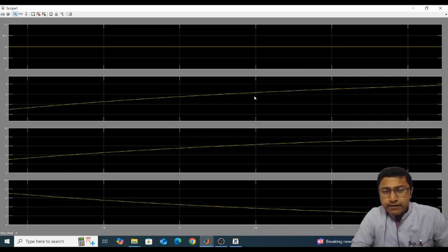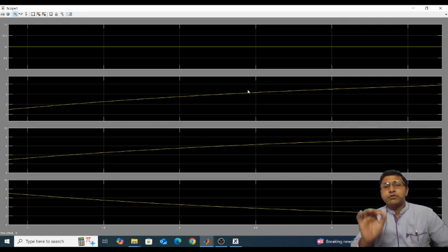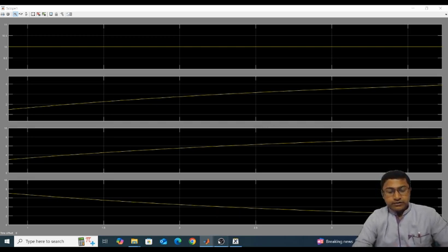At 2.5 millisecond, the inductor current crosses 3 ampere and is more than 3 ampere. We can say that at 2.5 millisecond it is nearly 3.16 ampere. So it is a clear concept of the time constant and a nice explanation. From here we can easily define the time constant and the other parameters in our simulation. So this is all about the first order series RL circuit. It is very simple.